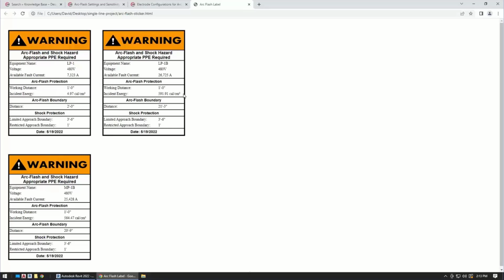okay, for this incident energy, here's the stuff that at our facility you actually wear in that case. So they take this back to their book, or their sheet on the wall, and they put on the appropriate stuff based upon what they actually have. So that's the actual workflow the electrician is going to use in the field. They look up the incident energy that you're providing on the sticker, go match that to the vests and the coats and the gloves that actually exist in their facility, or that they've got in their truck or whatever that is.